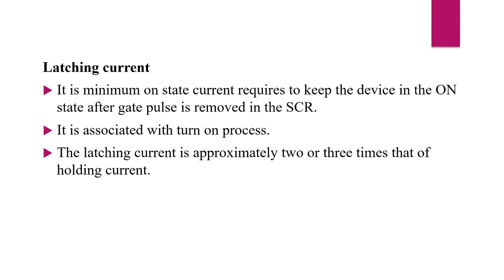Latching current is the minimum on-state current required to keep the device in the on state after the gate pulse is removed. It is associated with the turn on process. The value of latching current is approximately 2 to 3 times that of holding current.